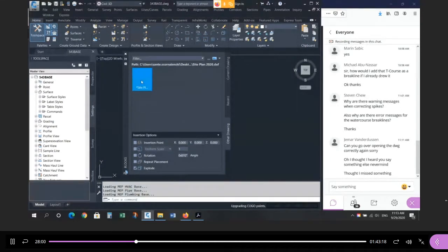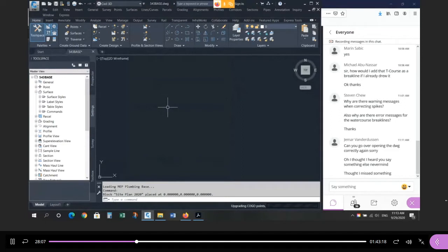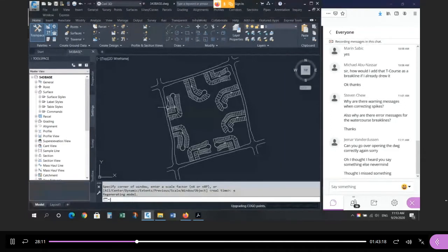And then you can go up to the file and double click, and it'll insert it into the drawing. Okay? You can close this. If you don't see anything, Z, enter, E for extents, enter, and you should see this. You can kind of see the shape looks familiar, right? You can see the bounding road that goes all the way around the 4 sides is the same shape as the topo. Okay, so it is geo-referenced. It is related to the topo that you were given.